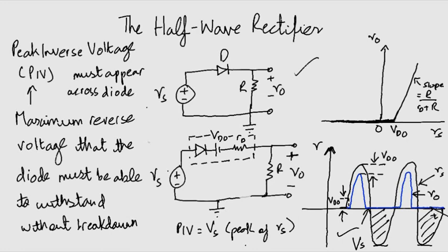Note that if the input signal is small, the circuit will not function properly. For example, a signal in millivolts will not be able to cross the threshold Vd0, and the diode will always be cut off.